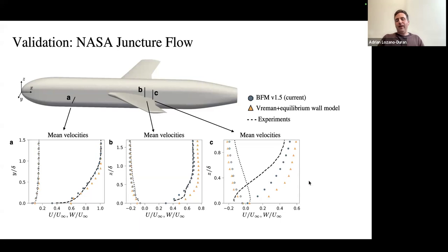But we are not predicting that separation well. One reason is also, again, that we have very few points. We are testing the model in extreme conditions where the grids are very coarse. If we keep refining, we get much better. Also, the other models get better. But the idea is that we tend to get always closer to the true solution. So we are always pushing the solution in the right direction.